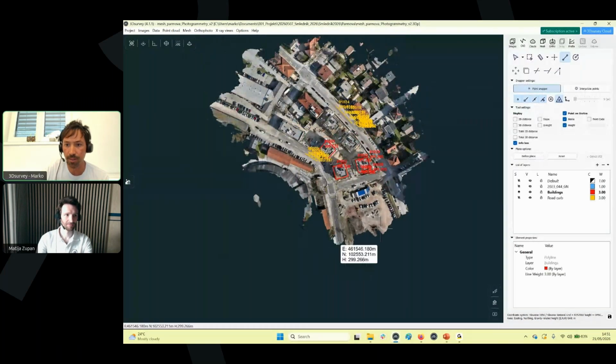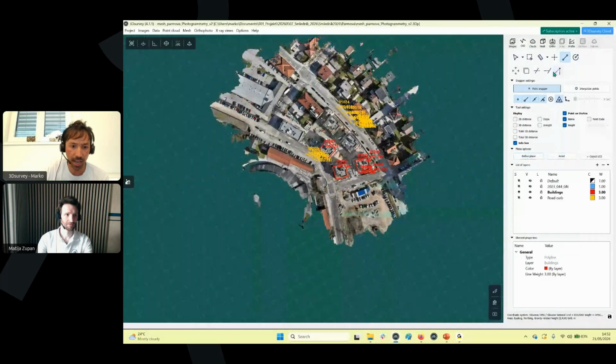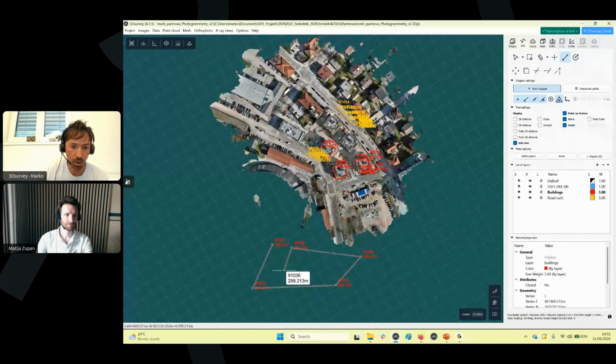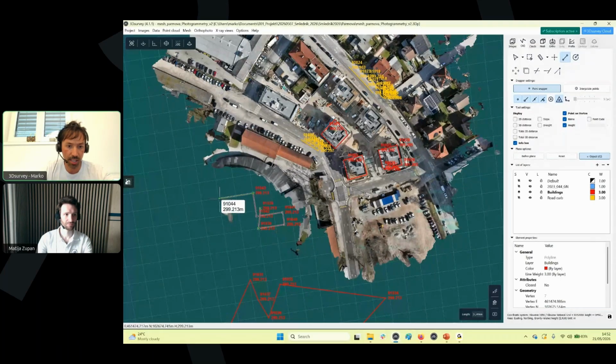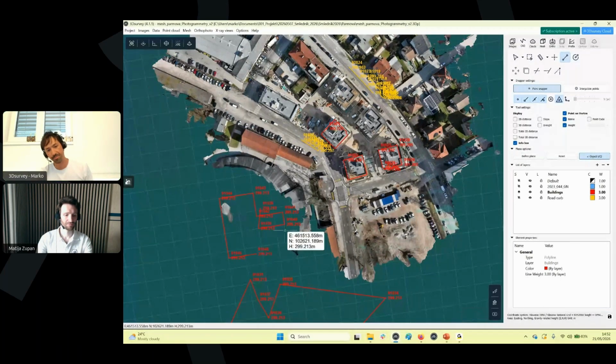But if I go and define a plane here, I can go and place points anywhere outside of the model, or if there is a hole in the model, easily with the help of the plane. And F8 gives me the perpendicular to my last line, and in this way I extract perpendicular lines.